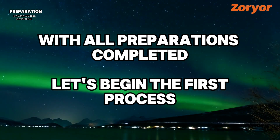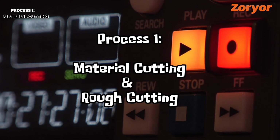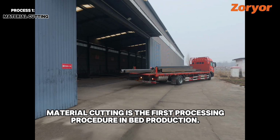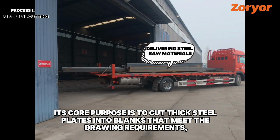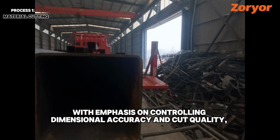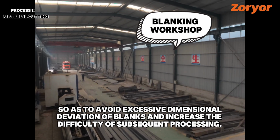With all preparations completed, let's begin the first process. Process 1, material cutting and rough cutting. Material cutting is the first processing procedure in bed production. Its core purpose is to cut thick steel plates into blanks that meet the drawing requirements, with emphasis on controlling dimensional accuracy and cut quality, so as to avoid excessive dimensional deviation of blanks and increase the difficulty of subsequent processing.